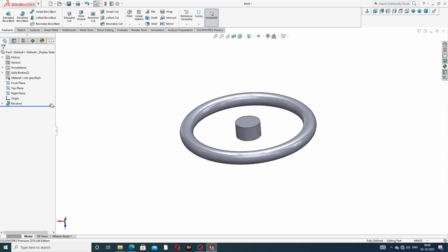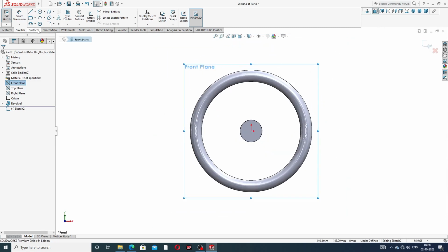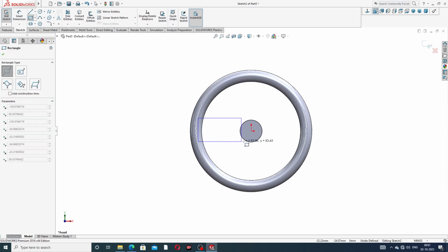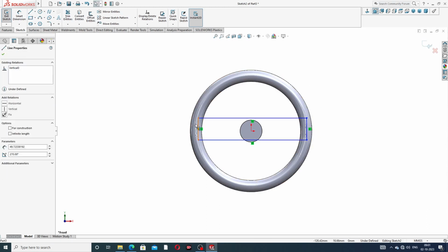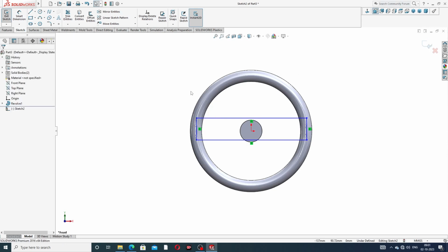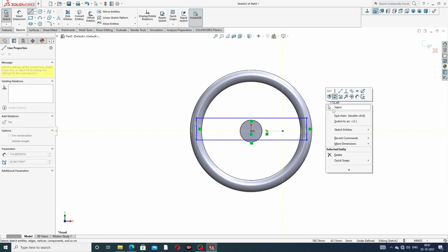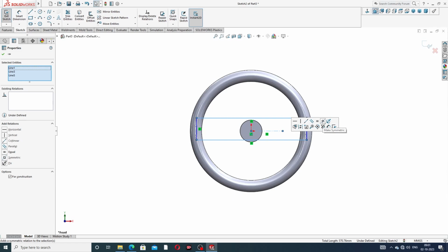And again, select a front plane and sketch normal. Select a corner rectangle, and corner rectangle is drawing this. At first, draw a center rectangle. Center rectangle is this, and this line, and press the control button, and this line is a selector, and use make symmetric.